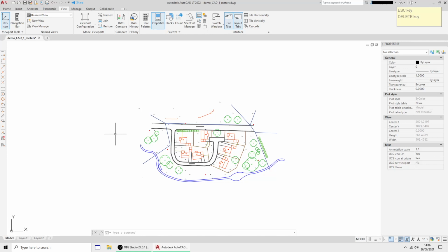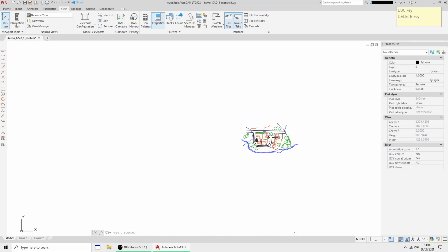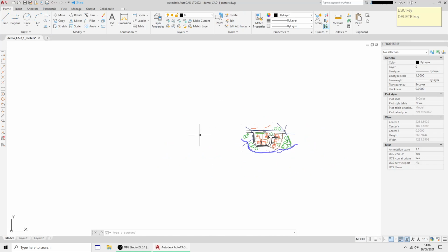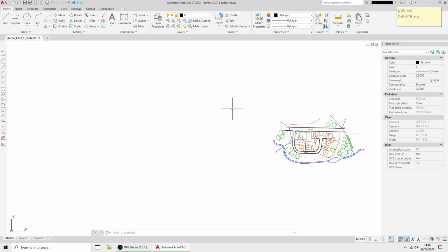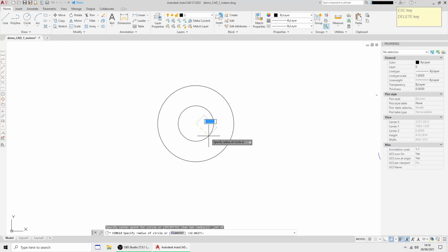If entities have got Z values and you go to measure things and plot things and whatever, you need to be aware of the Z axis in case you start meeting these situations. So we're going to very quickly talk about it and start by over here. I'm just going to plot a circle and then draw another circle inside that circle, locked onto its center,